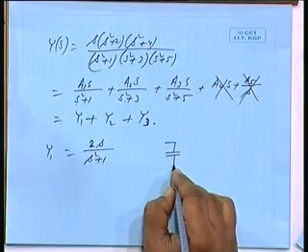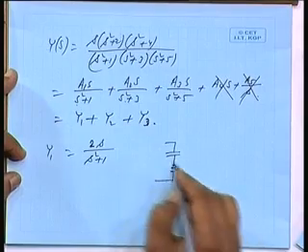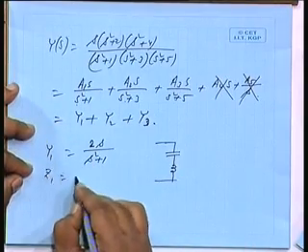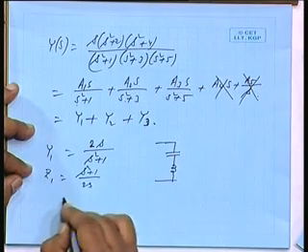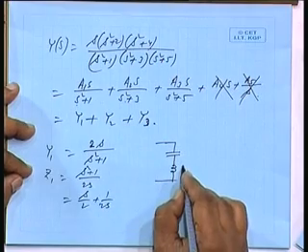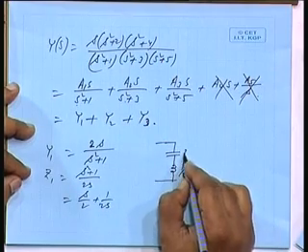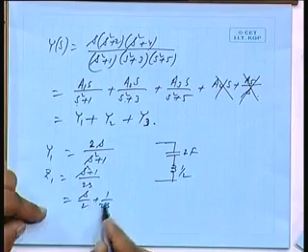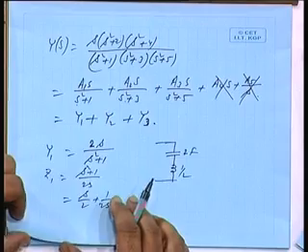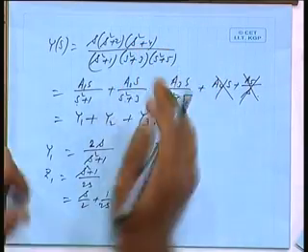At that time, at a very low frequency, inductance is 0. It is a series combination. You see, if y1 is this, corresponding z1 is how much? S square plus 1 by 2s. That means s by 2 plus 1 by 2s. So half Henry inductor and 2 farads capacitor will give me this impedance, whose admittance is this. So each admittance you just invert and then separate, you will get the corresponding LC values. Is that all right? So similarly you get another LC combination,